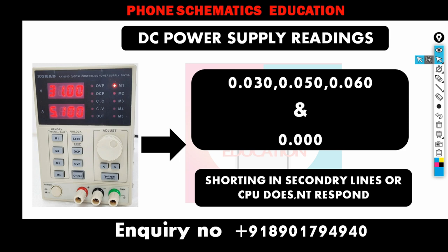Your power on, boot up, when it gives the voltages, a buck voltage to the CPU, somehow the buck shorts, or any LDO shorts. That's why it goes back to 0. When it produces the buck voltages for the CPU, the CPU does not respond, the feedback does not come from the CPU, and the power shuts down. Maybe something is wrong in the circuit or with the CPU.